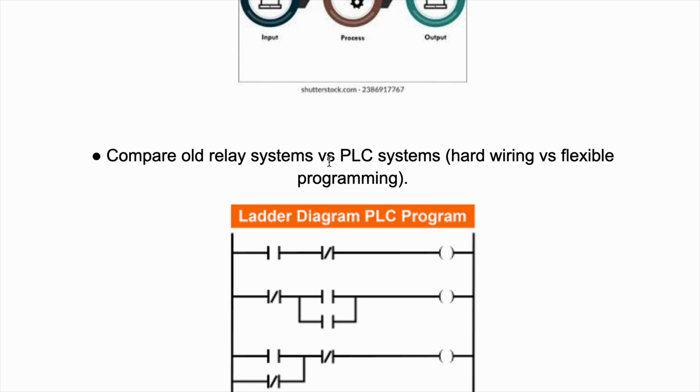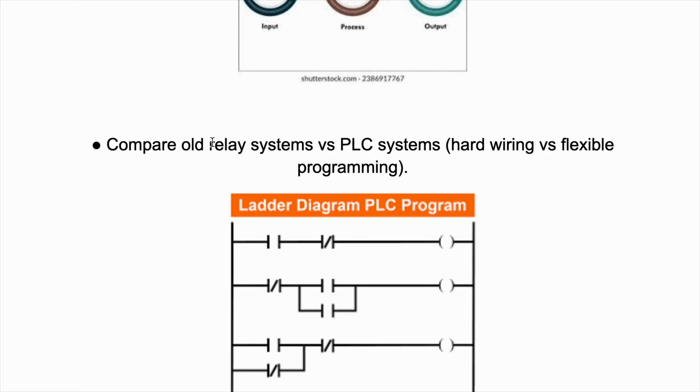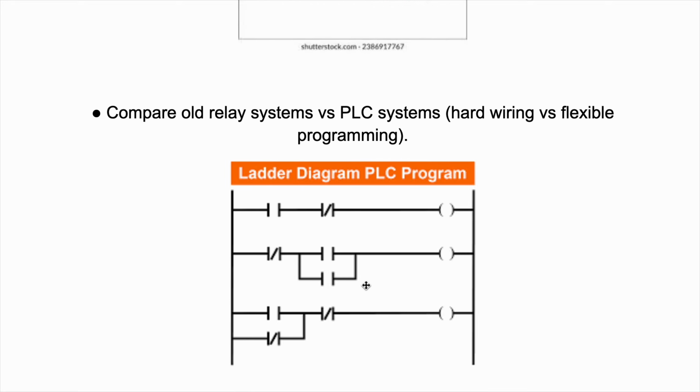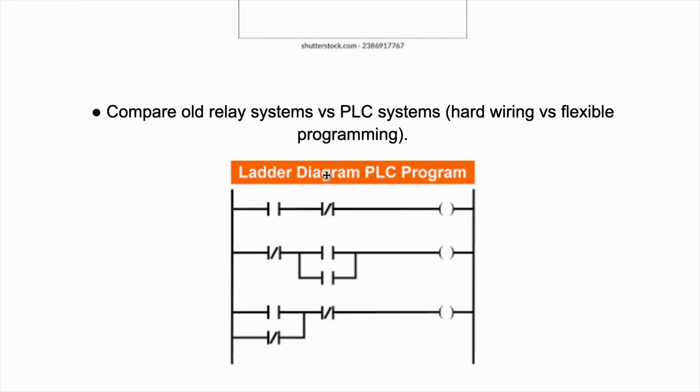All-relay systems versus PLC systems: if you don't use PLCs, you need big panels with a lot of wires, a lot of connector terminations, a lot of relays and contactors, everything. But here, it's all in the PLC, a little box, and you program with your laptop with your ladder diagram.